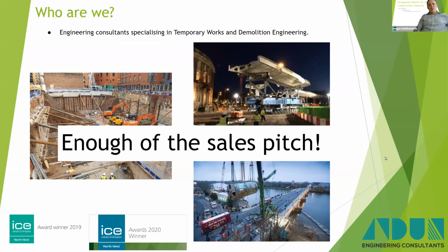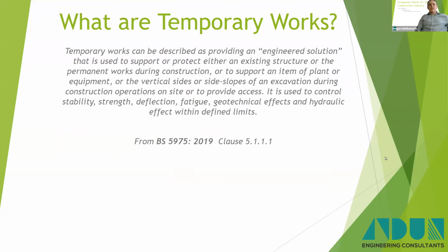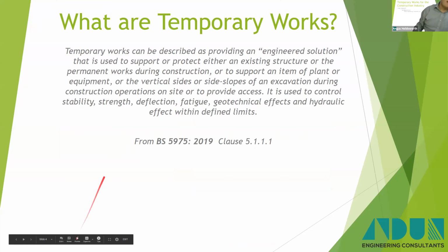What are temporary works? The best place to look is BS 5975 2019, clause 5.1.1.1. I'm not going to read out that description from 5975 because it's quite word heavy, and it's basically one massive sentence from here to here, which is not ideal, but it basically says almost everything is temporary works when you read that.